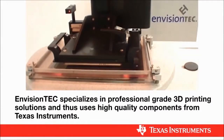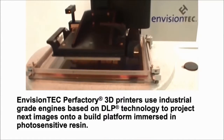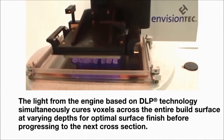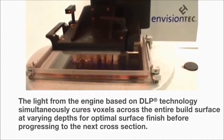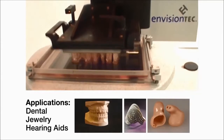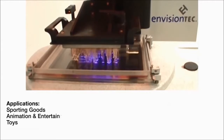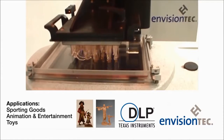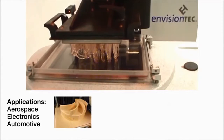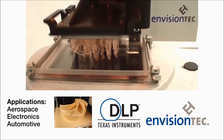Digital Light Processing, or DLP. Digital light processing is another 3D printing process very similar to stereolithography. Both work with photopolymers. The DLP technology uses digital micromirrors laid out on a semiconductor chip. The technology is applicable for movie projectors, cell phones, and 3D printing. The material used for printing is liquid plastic resin placed in a transparent resin container. The resin hardens quickly when affected by a large amount of light.